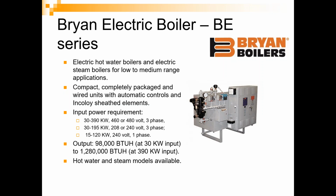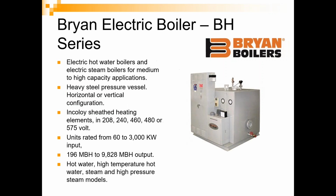The BE series from Bryan is a very compact electric boiler with automatic controls, Incoloy sheathed elements. They have 460 volt available, 208, 240, and even 240 single phase. They have output sizes from 98,000 all the way up to 1.28 million BTUs. And they do make this in both hot water and steam models.